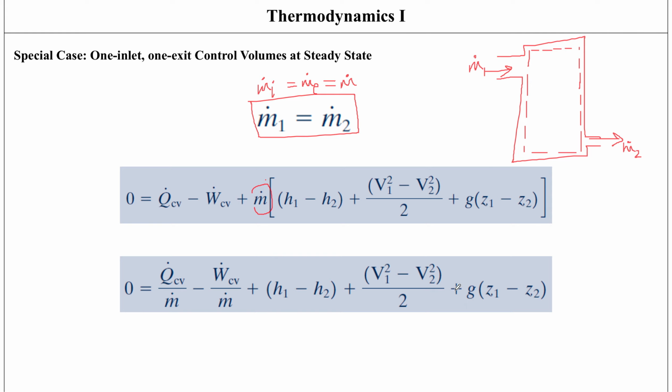So with this equation, usually when we're looking at this kind of system, because there are no rotating shafts in here, and there's no electrical effects taking place, this term usually drops out. This is not always the case, but usually this is what happens. Other than this, the potential energy term usually drops out too, because the elevation changes aren't taking place to an extent where this would have an important effect. This is usually negligible, so this drops out as well.